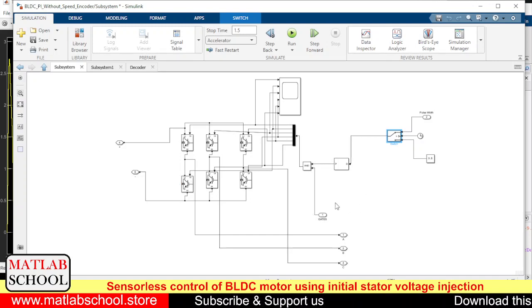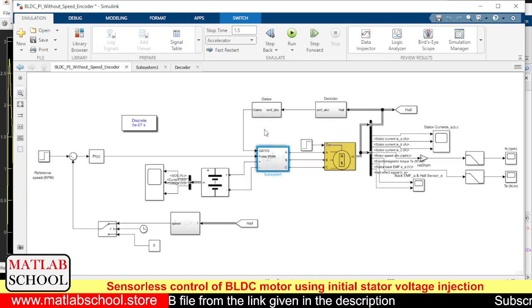So as you can see here, you can see two things. One is the control logic for controlling the speed, and the other logic which are coming from these two blocks. So these two blocks are responsible for deciding on which switch to excite at that particular time. In the sense, we'll be trying to excite the stator winding which is very nearer to the rotor at that point in time. So that's the logic behind this.